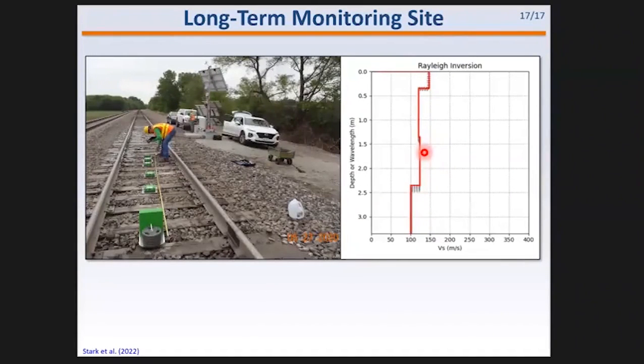Other questions? You assumed 8 inches under your control site for load distribution. Did you assume that same value for the fouled site? And is that appropriate, given the fouling is going to have a completely different state?